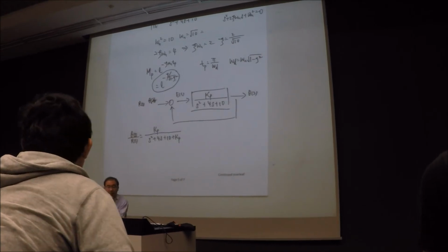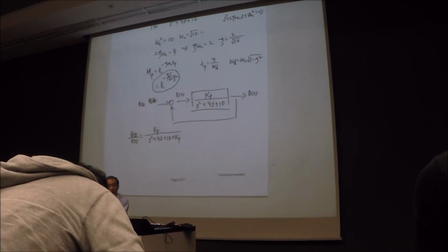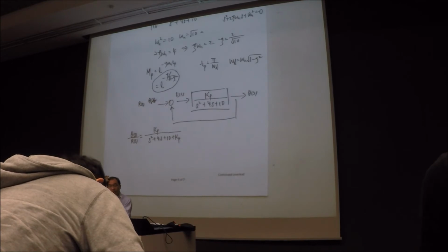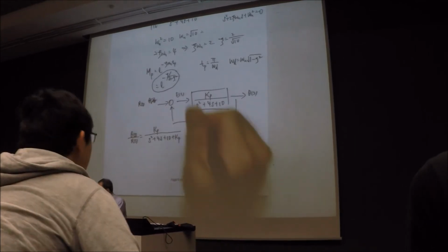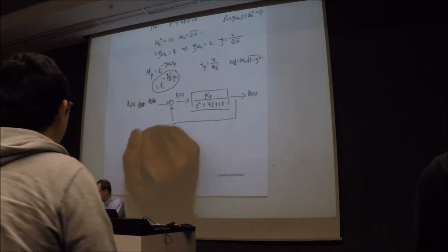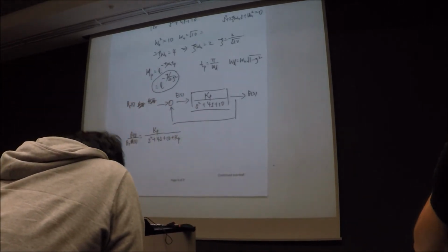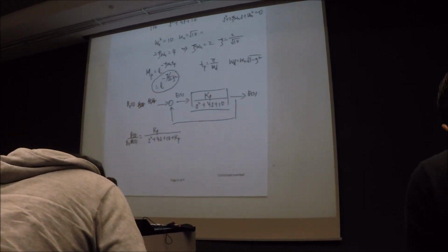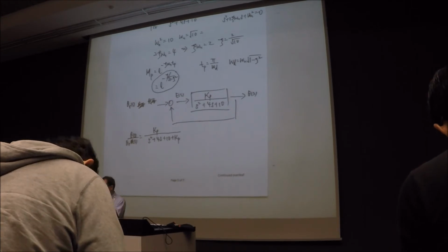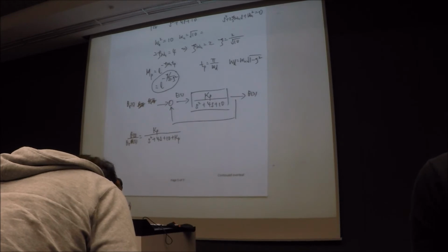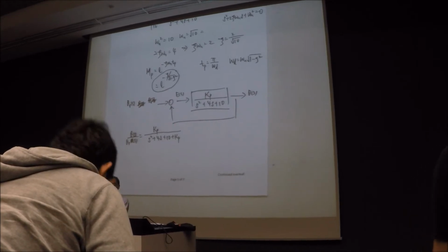Okay, proportional control with gain Kp equal to 10 is applied. Calculate the closed loop natural frequency and damping. What's the steady state error in response to a unit step input in theta R(s)? Calculate the resulting maximum overshoot and so on. So from this, what is your closed loop damping and your closed loop undamped natural frequency?